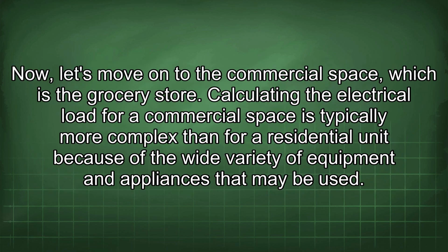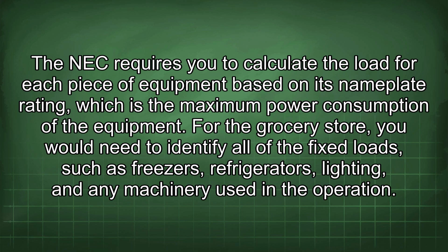Now, let's move on to the commercial space, which is the grocery store. Calculating the electrical load for a commercial space is typically more complex than for a residential unit because of the wide variety of equipment and appliances that may be used. The NEC requires you to calculate the load for each piece of equipment based on its nameplate rating, which is the maximum power consumption of the equipment.